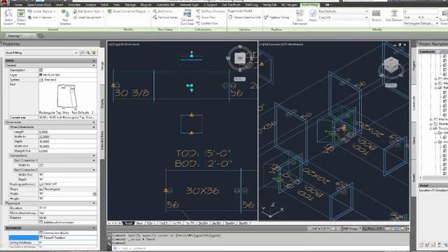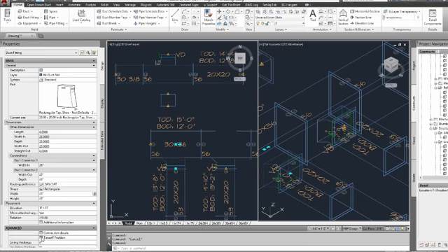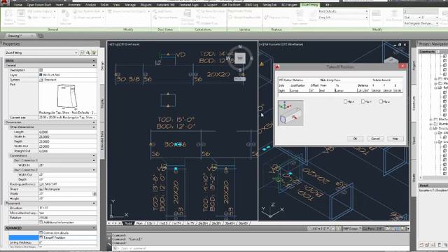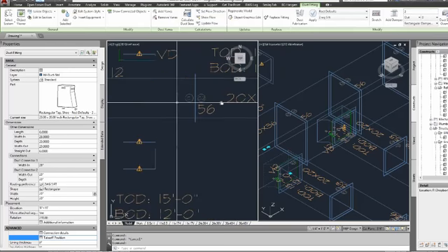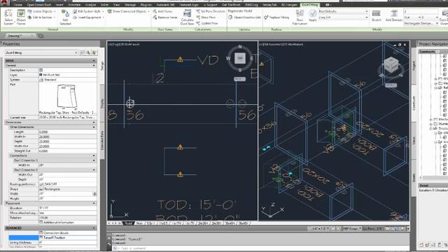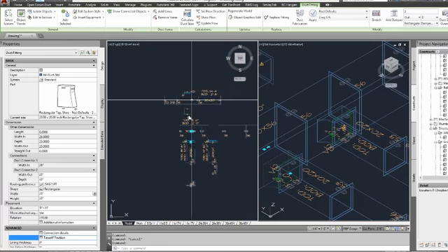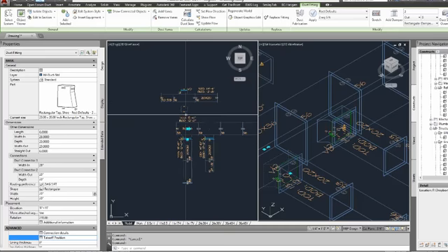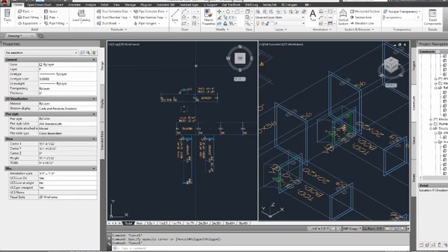It's not on the same side as this duct. And both of those are set to the right side. We come down and verify this one again. You can see that it's set to the right side. So as I mentioned, this is connector 1, this is connector 2. So you look at the duct from right to left, and that tap is actually on the right side. It's just because the orientation of the duct it's attached to is rotated. So that makes a very big difference when routing duct on how the taps are.